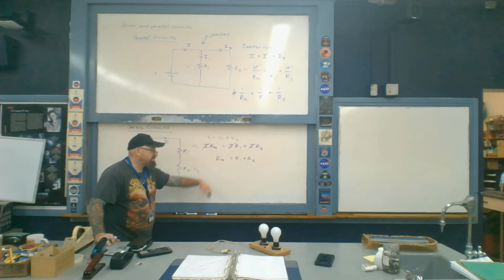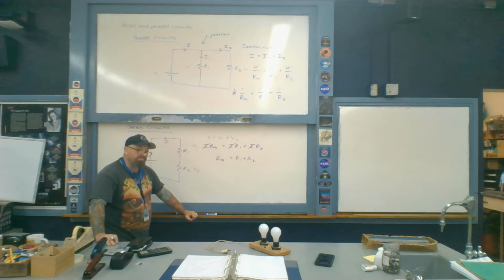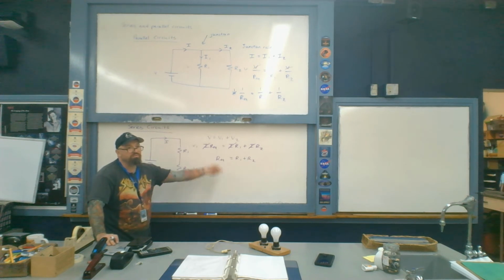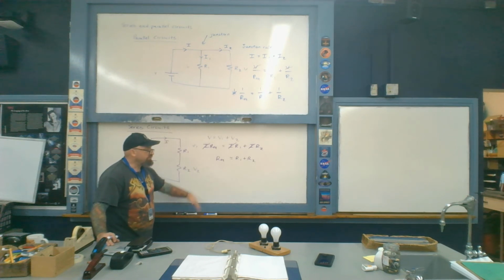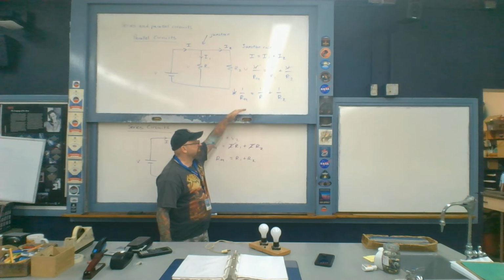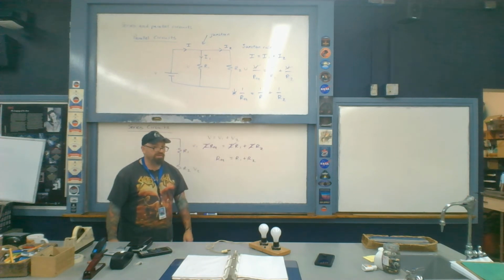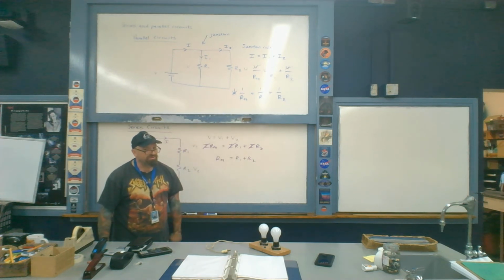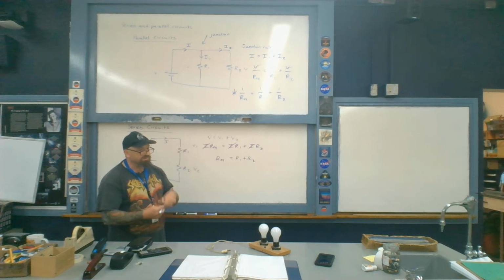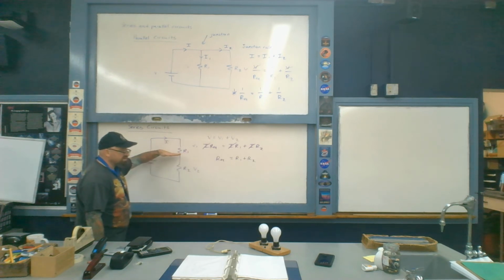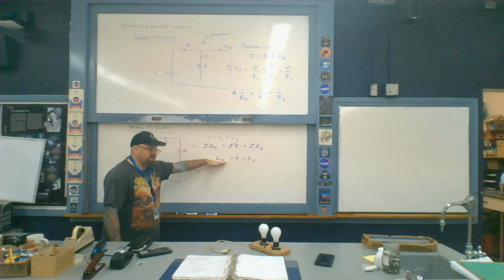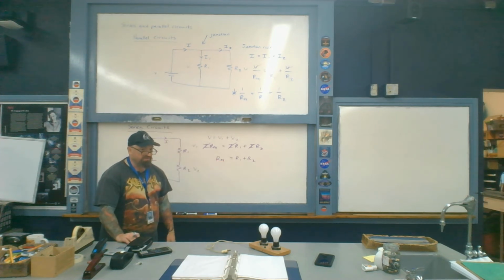Okay, compare this expression here to the equivalent capacitance calculation from chapter 24 for capacitors in series. If you make that comparison back in chapter 24, it was the 1/over relationship to find equivalent capacitance. So you end up with two similar equations here for equivalent resistance as you do for equivalent capacitance. Well, you'll notice that they're backwards from each other. Sometimes this is a little bit difficult to remember. So for a series circuit involving resistors, just add them up. For a series circuit involving capacitors, it's the 1/over relationship.